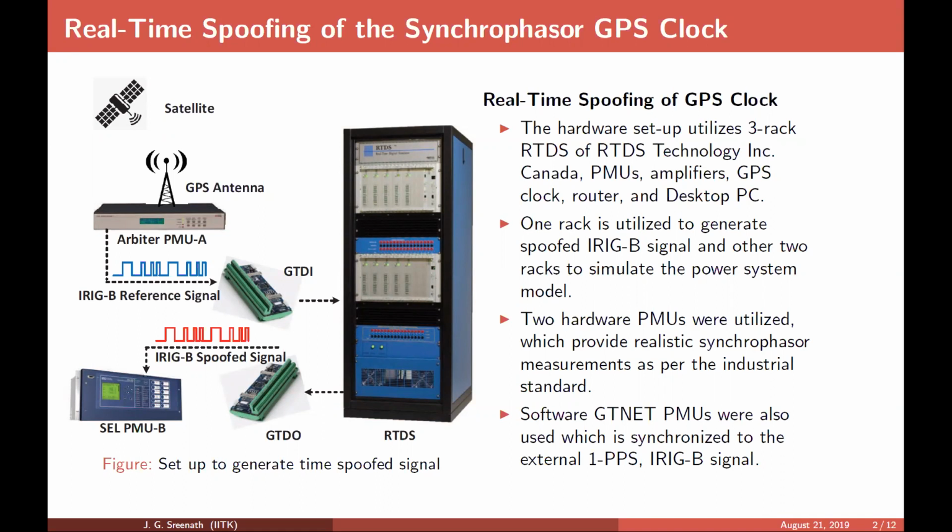This particular clock generates a signal known as an IRIG-B signal, an inter-range instrumentation group code. So the IRIG-B code, as you can see here, is being used for PMUs. As soon as the data comes in, the IRIG-B code is used for the correct timing information for the PMUs. And this is the information that you get with the data, the timestamped information.